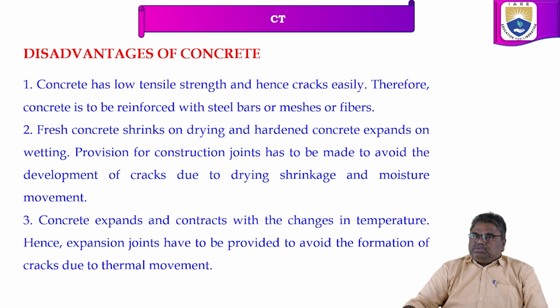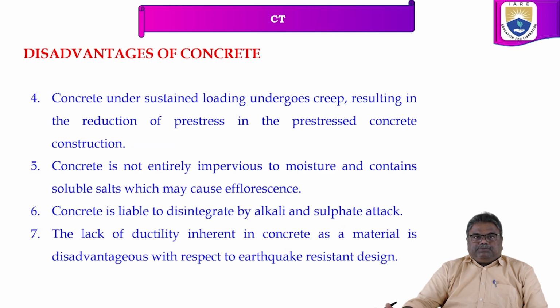And the third one is that concrete expands and contracts with the change of temperature. Yes, concrete will expand and contract with the temperature, and expansion joints have to be provided to avoid the formation of cracks due to thermal movement. So we have to provide the expansion joints at particular intervals during the construction.